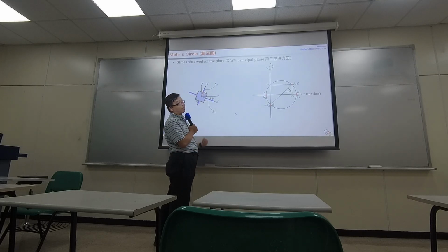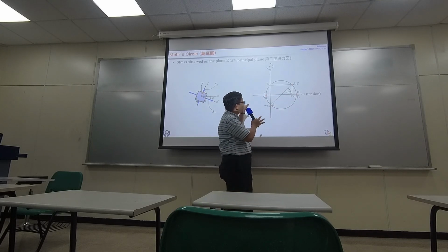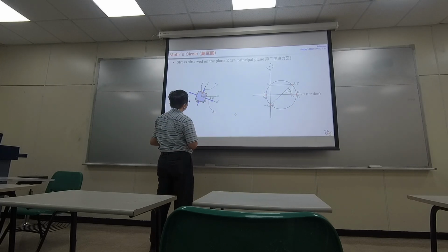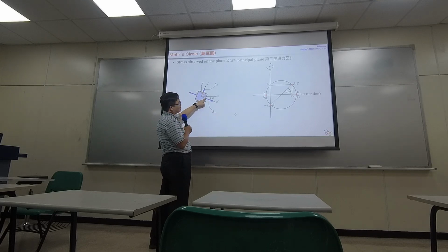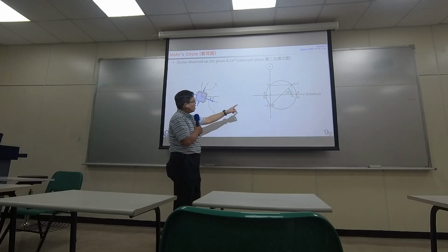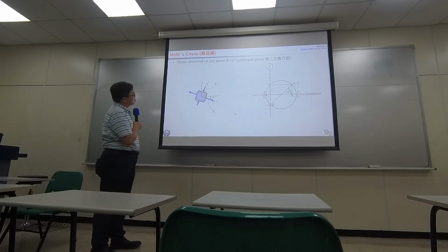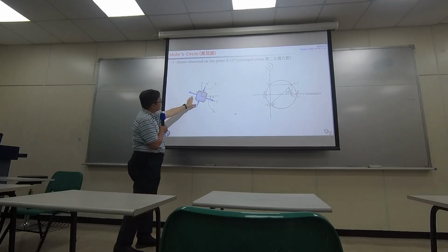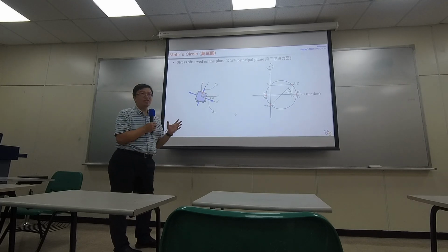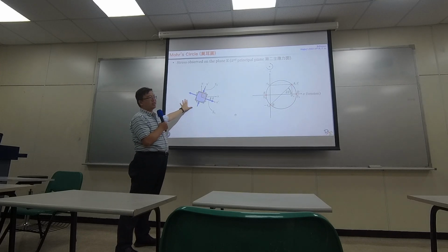And it's the second principal stress. Okay, so S1 in this condition, based on the drawing I made, along this observation angle, horizontally is carrying the largest normal stress, S1, and vertically is carrying the most negative normal stress, a compression stress. So here, if you observe the element in this way, you don't see shearing stress. So usually, we will make our design based on this angle.